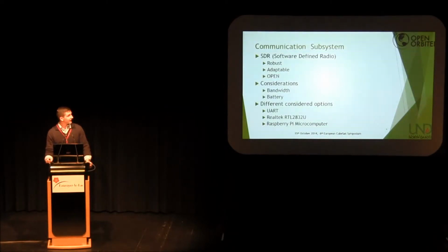Then moving on to the communication subsystem. We decided to go with a software-defined radio implementation because this allows for additional flexibility and potentially low cost. What an SDR does is essentially replace hardware components in a traditional radio setup with software configurations that can configure the radio in real time. That includes things like switching frequencies, modulation types, and bandwidths. This is good for the unpredictability of space. And of course, we'd also like it to be open source so the end user can modify it to tailor to their specific mission needs.